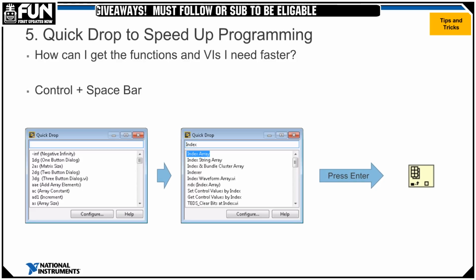You can just start typing in the name of whatever function you're looking for, and it will find it for you. So in this case, I opened Quick Drop with Control and the spacebar. I started typing "index" because I knew I was looking for this Index Array block. It figured out what I was looking for, and when the block you want is highlighted blue, you can either press Enter to have it appear on your mouse pointer so you can drop it, or you can just click anywhere in the block diagram or the front panel to drop that block.